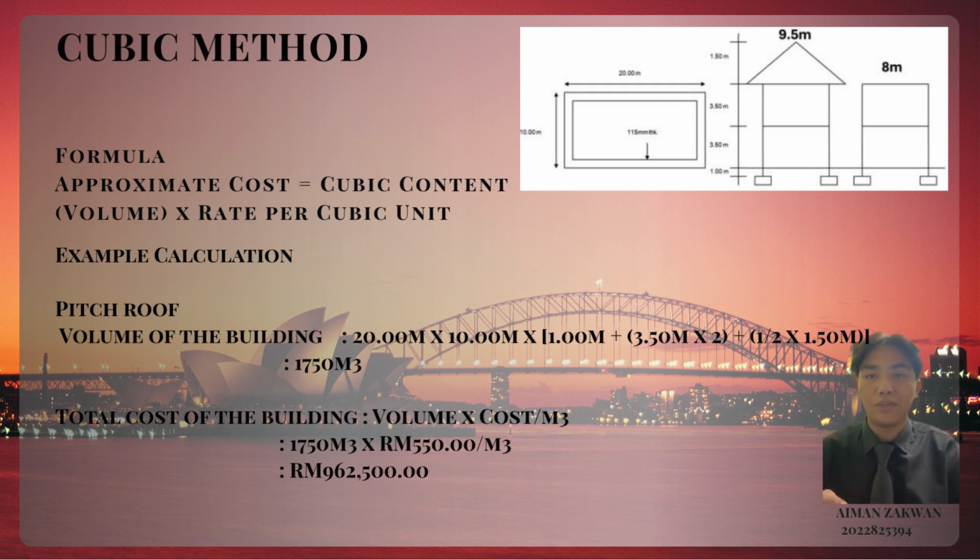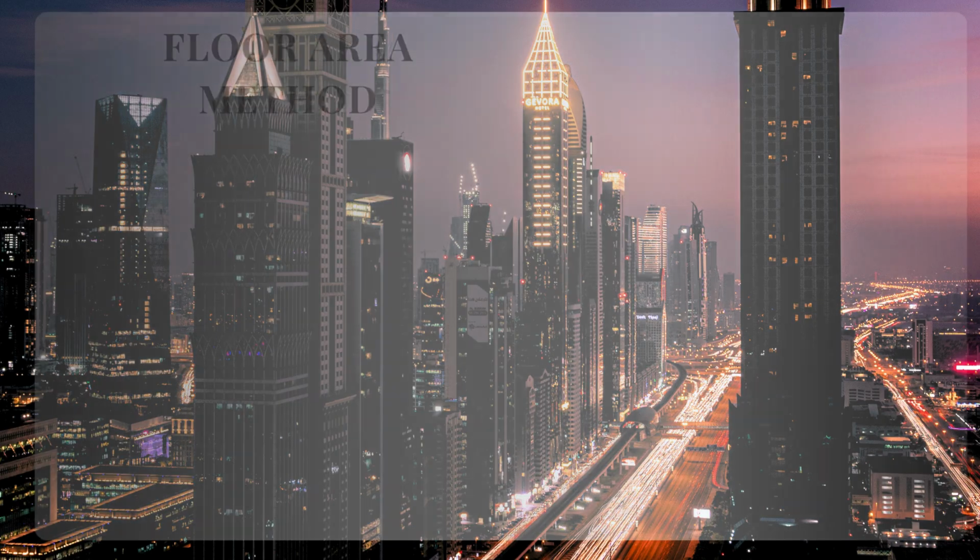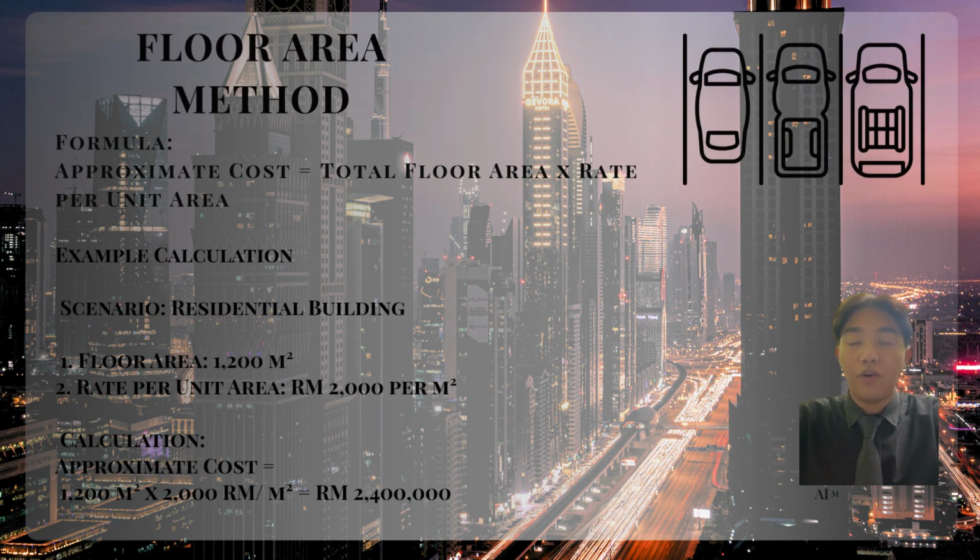Then we will need to calculate the total cost of the building, where the volume will be multiplied by cost per meter cube, which is, I will take for example 550 ringgit. Then I will multiply it with 1,750 meter cube, and I will get the answer 962,500 ringgit.